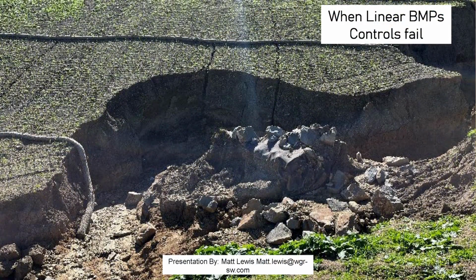And last year, all they really had was just rock check dams, hydro seed, and on the sides they had the linear breaks. And all the water just went underneath all the check dams. And it was literally 40 feet deep at some spots, maybe even deeper than that, and probably 30 to 40 feet wide. I've never seen erosion like this before. Rather impressive.